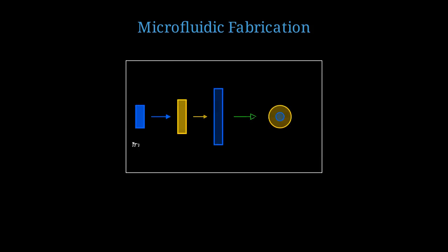How do we actually make these complex structures? The answer is microfluidics. In a microfluidic device, we have 3 coaxial channels. The innermost injects the core aqueous phase, the middle channel provides the oil phase, and the outermost channel supplies the continuous aqueous phase. Precise flow rate control generates monodisperse double emulsions.